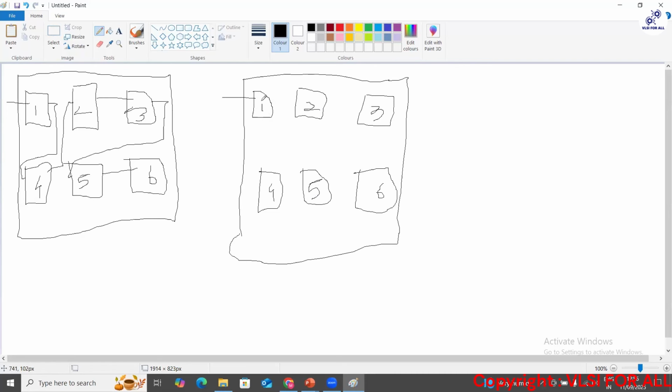So instead of flop 1 going directly to 4, I will state, let the path go to flop 2, because there is no logic cloud in between that the data has to be transformed through. If you pass a 1 over here, the 1 should come over here, and finally the 1 should only come at the output. There is no combinational logic cloud present between these flops. That is present only in your functional mode, not in your scan or debug mode.